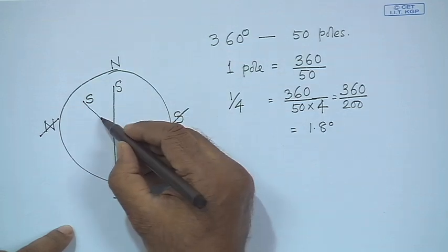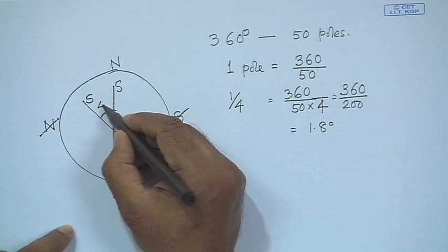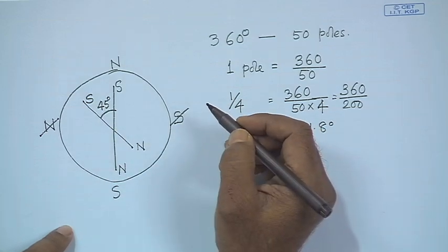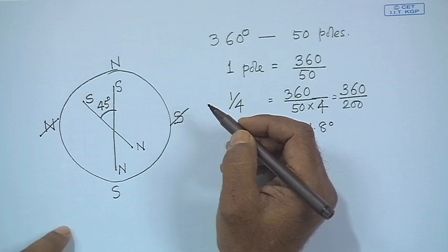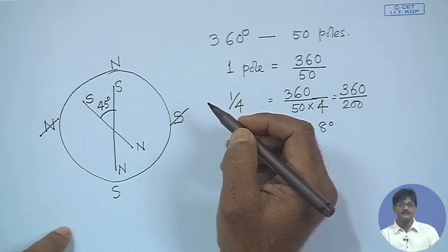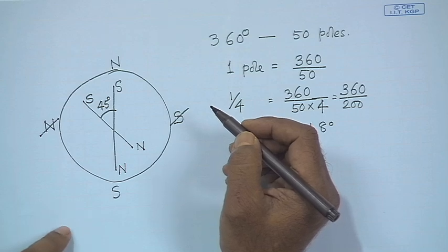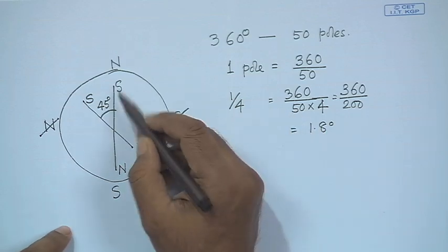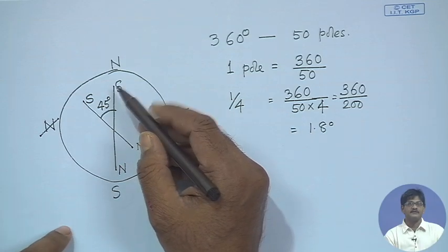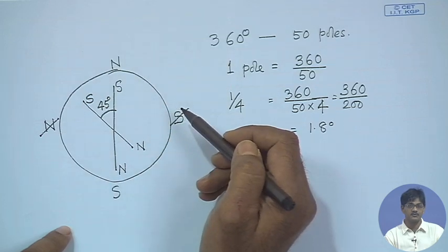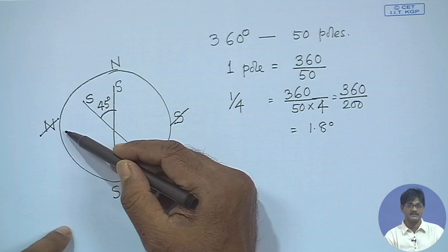Therefore, instead of the 90-degree movement which was being achieved by this simplified model, I am going to have a 45 degrees movement. That means I am effectively dividing the step into 2. I am effectively achieving half a step. But the problem is that the power to the motor is being halved, and therefore, the torque that it can handle becomes less.